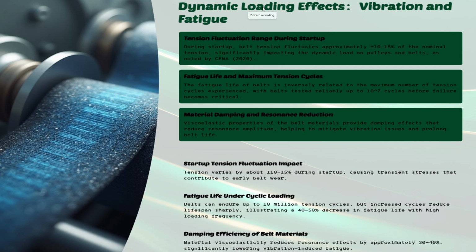To combat these destructive forces, manufacturers build viscoelastic properties directly into the belt materials. This built-in material damping absorbs the shock of rapid movements, reducing destructive resonance amplitudes by 30% to 40% and significantly lowering vibration-induced fatigue to prolong the system's life.